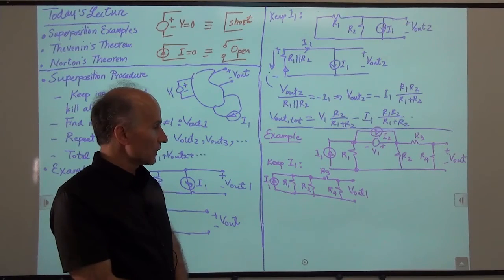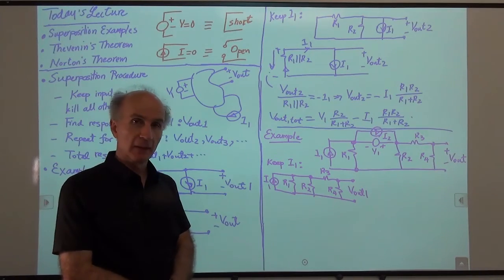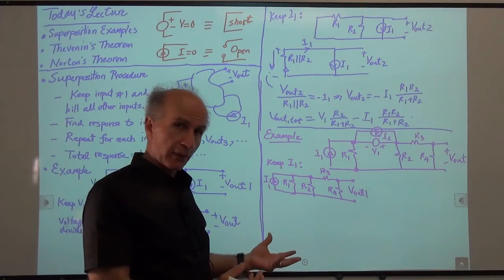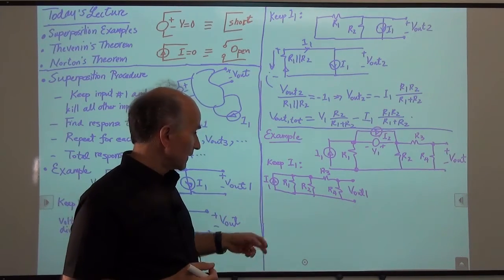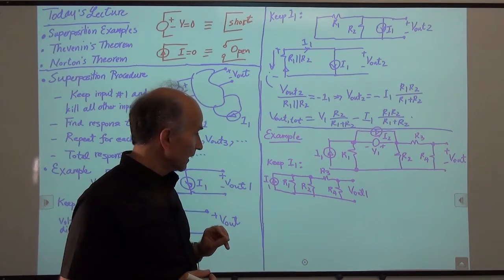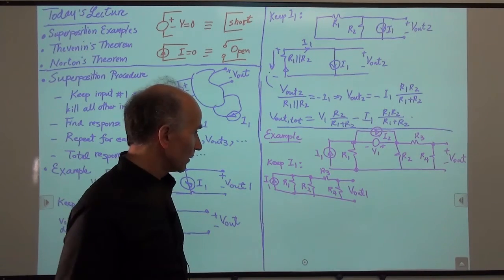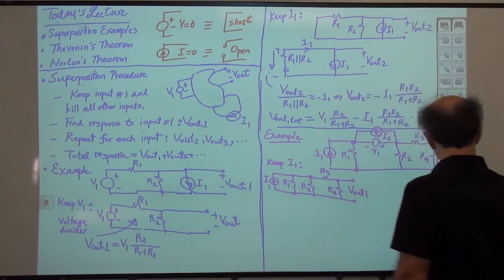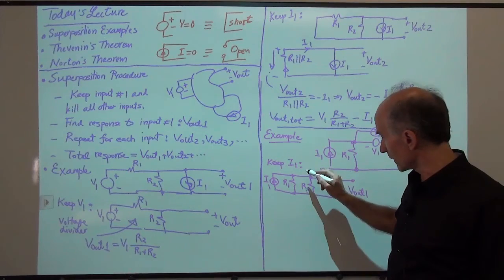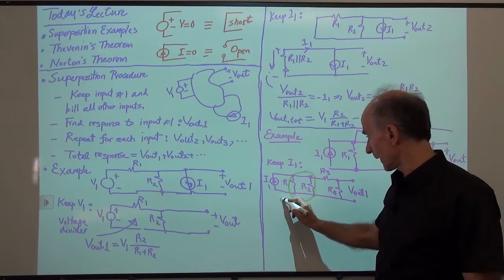Okay. So we have V out 1 here, and we need to find it. How do I solve this circuit? Well, that probably needs some node analysis or something. We can try to apply some shortcuts based on our previous knowledge. We see that R1 and R2 are in parallel. That's great. We can just consider it as one resistor. And then we have a resistor here and a resistor here. So let's play a little game here. I'll try to do this slowly so that you can follow. Okay, so this is one resistor. So we call that RA.